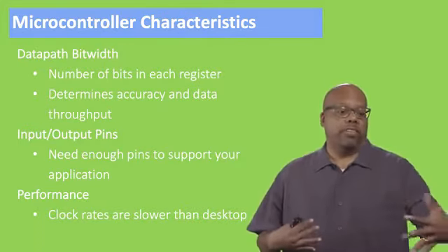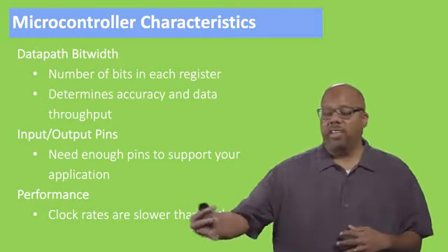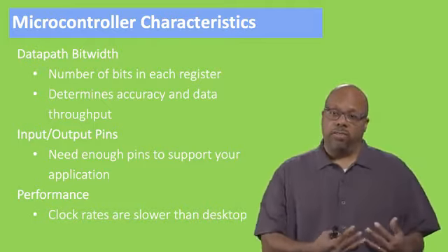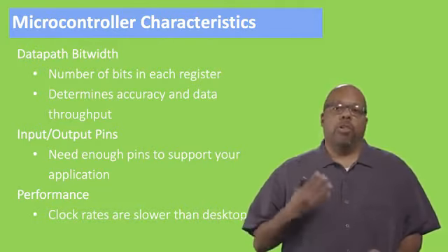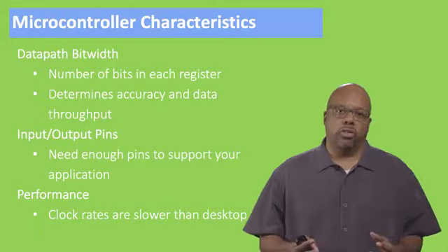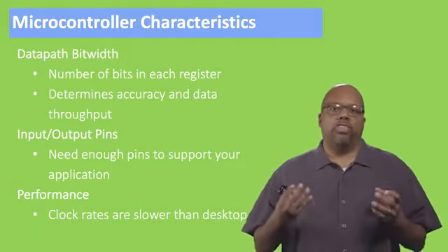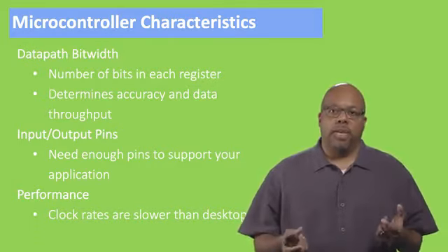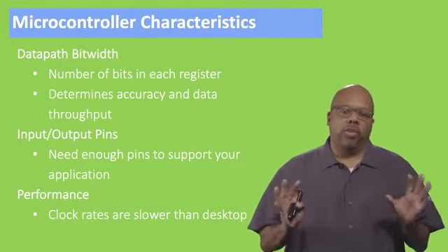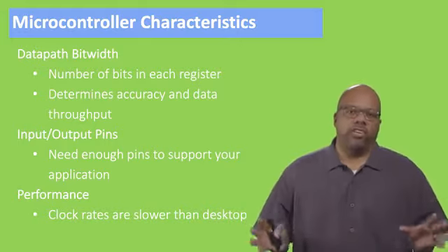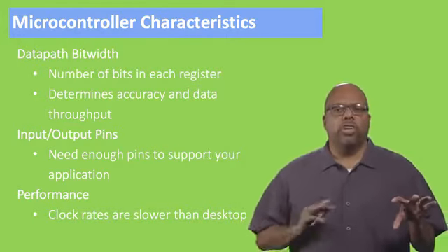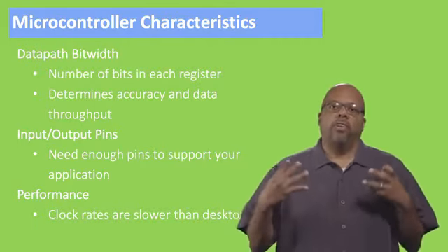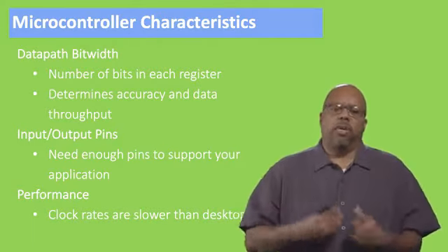So maybe you need 3 pins to connect to one integrated circuit and 5 pins to connect to another, and so on, depending on what the circuit is, how many pins it has on this interface. And you can easily chew up all the pins. You can easily use up all the pins in a microcontroller, because these microcontrollers generally don't have too many pins. So you have to be careful about how you use the pins. That's why very early in the design process, you have to sketch out your design, figure out what the different components are you going to use, and how many pins each one of them needs to talk to the microcontroller. And so you can get a number like, say, okay, I need 40 pins.